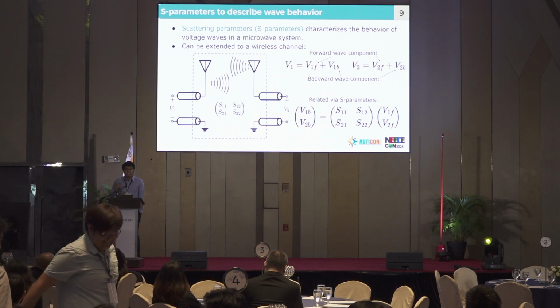At each antenna, you have a voltage that you measure. You can decompose it into its forward component and backward component. And you can relate these components using the S parameters.